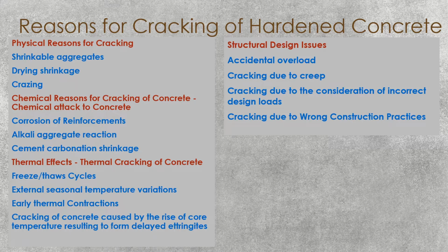Cracking due to consideration of incorrect design loads. If you haven't considered the correct design load, and instead of the required load you have done a design for a smaller load, there may be excessive deflection or structural cracks, even structural failures. As an initial warning, there may be cracks in the concrete with the increase of the load.